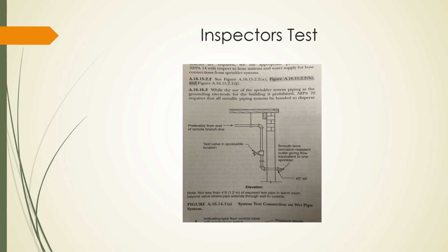Now on the other end, at the alarm check valve, the alarm check valve will be identified by size. So you have that piece and you can work on that piece. So you've got these two pieces at either end. No, an inspector's test doesn't necessarily have to be at the end, but for the most part, it's going to be at the end of the system for a wet system. And you'll have the inspector's test at one end, giving you one dimension. You'll have the alarm check valve giving you another size.